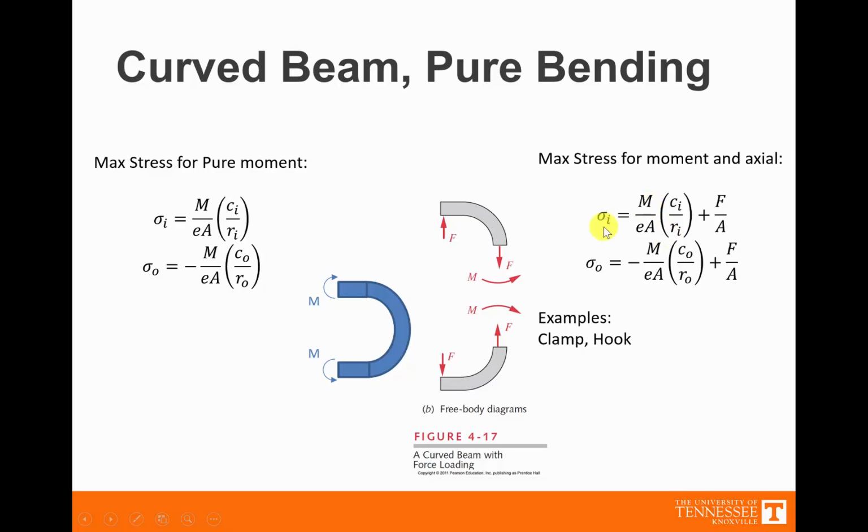In this particular loading situation, there are no transverse shear forces, and there are no twisting forces that would be rotating the hook the other direction, so out of or into the page, or maybe around the F. So there's no torsion occurring. So in both of these cases, if those other cases existed, we would have to check the full stress state. As it is, this will suffice for the stress state that's occurring on the inside edge of that break and on the outside edge of the break. And there would not be any other stresses in any of the other directions. No other normal stresses, nor any other shear stresses. So these will define our stress state at those locations.